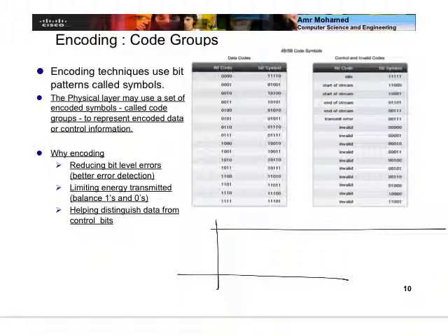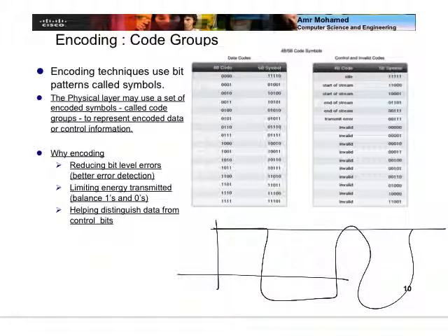Whereas if you have changes in the bits, you tend to have positive and negative, so the average voltage goes towards 0 voltage. If the average voltage goes towards 0, then the average power, which is proportional to that voltage, tends to be low. So by introducing these extra changes in the bits, we can reduce the average power.